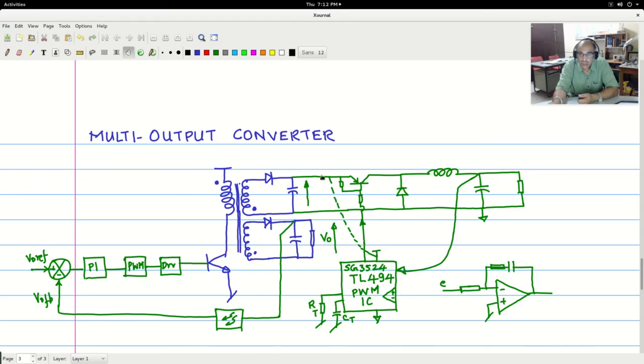Now instead of the linear regulator, this buck regulator can replace that, and then this will definitely have a much better efficiency, because this will not incur losses except for the on-state drops and things like that. The efficiency of this will be much higher than the linear regulator.